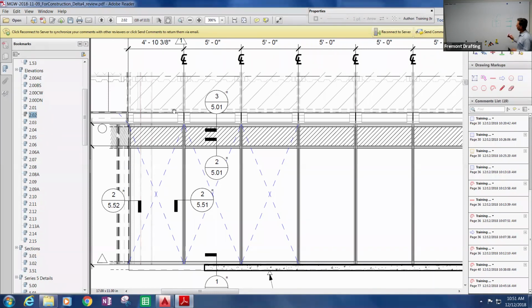And so on our stick walls, if I was doing that on a stick system, do you understand what I mean when I say stick wall? So it's field installed. It's a bunch of parts and pieces. You go out there, erector set, put it up, and then put the glass in. So I've gone out and put my verticals up, and then we put our horizontals in, and then we put our glass in. So I've got extra horizontals there, so everything in the unit sort of gets squared there.